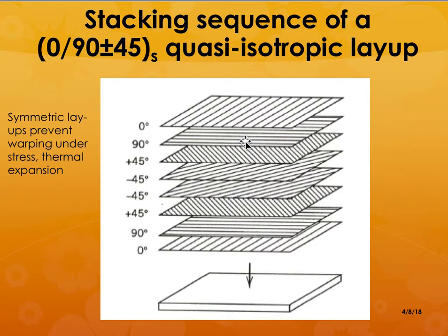So when you calculate the properties using the Excel spreadsheet, you will find that if you have the fiber orientations in those different directions, they will have different kinds of properties, and you will have very uniform properties that are almost equal in all different directions, especially if it is a quasi-isotropic layer.